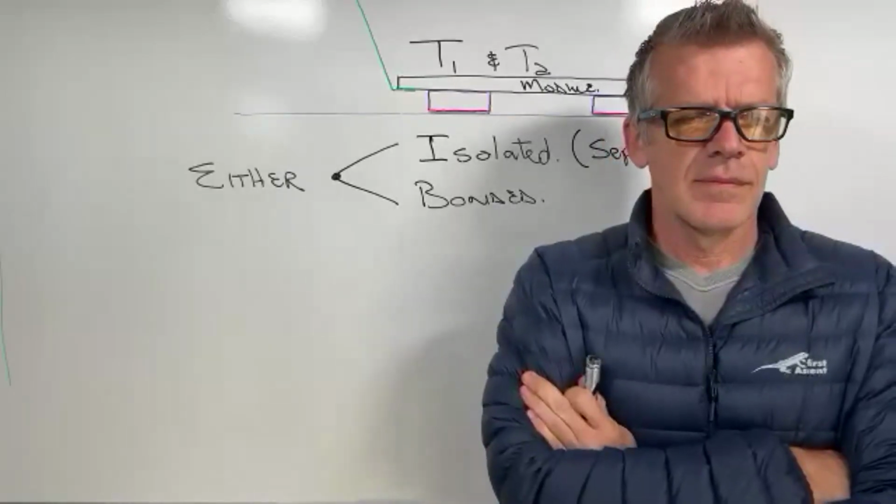So what we find at the moment, we're just talking about steel roofs now, and we've proved it now over 70 megawatts of projects, that the inverters come out standard with a type 2 surge arrestor.